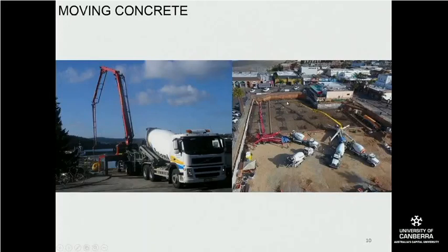Okay, now you can see that this is a very versatile thing. On high-rise buildings, what they do is that they attach the pump to the floors that have already been constructed, and it's pumped up the building still in that way. For small bits, they may actually just crane up a huge bucket of concrete to place in certain places.